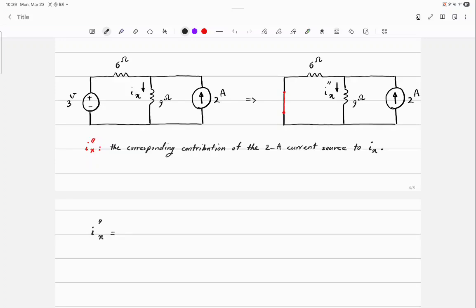You can find the voltage across the 9 ohm resistor by taking the equivalent resistance and multiplying it by the 2 amp current. Completely correct, but that's not the best way. Then current division? Current division. That's the smartest move here.